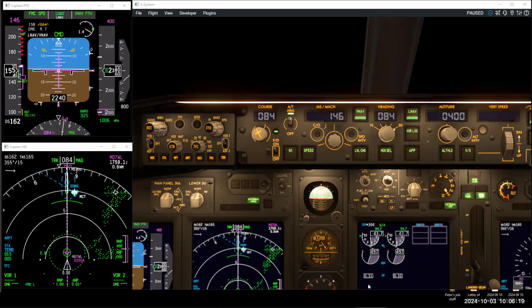So all of those items, 8 items, have been completed, and we've selected landing flap, and we've selected VREF 30 plus 5, and the speed is decaying to that now, as you can see. So, and we've got a good rate of descent, and we're not at Mike 07 Whiskey Lima, which is our final fix. We are just coming up on that.